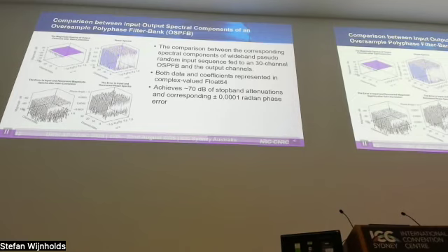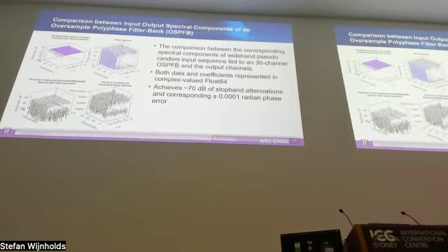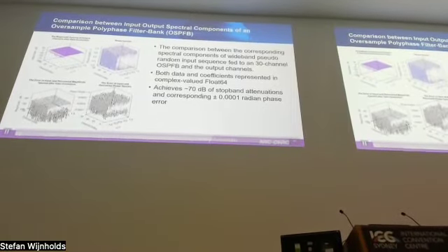Test signals consisting of uniformly spaced sinusoids of unique magnitude and uniformly distributed phases were generated using the fast Fourier transform. The top row of the figure displays the magnitude and phase spectra of the input segmented into 30 channels in red, alongside the results from the OSPFB function in blue. The bottom row of the figure shows the difference between the input and output magnitude and phase spectra after correcting for passband ripple.